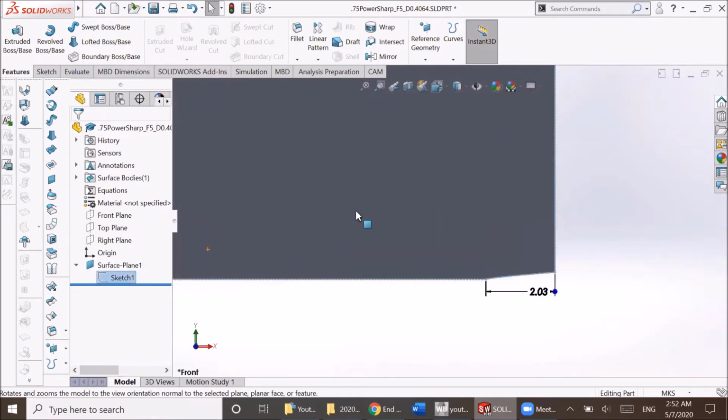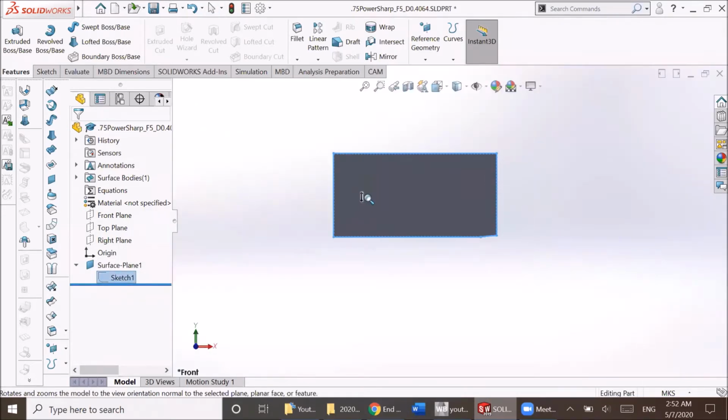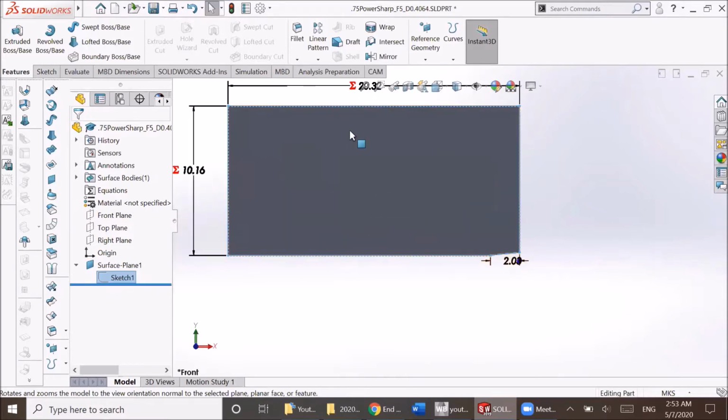So I have just constructed this simple geometry in SolidWorks, and I have made the enclosure, or the fluid flow region, about 10 times the reference length in the vertical and the upwards region, and about 5 times the reference length in the side region. The reason I like to use SolidWorks is just because it's very user-friendly. And you will notice that when you get to Design Modeler, it's not the most user-friendly software out there. So use whatever CAD software you're comfortable with before importing the geometries.